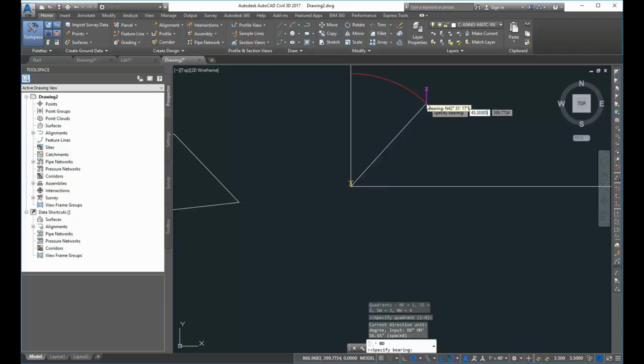So this is certainly different than what you're probably putting into your calculator. That reads as 45 degrees, 30 minutes, and 30.5 seconds. If my bearing was in decimal degrees, I would have to convert it to degrees, minutes, and seconds and put it in here. If you had a lot of them, then I'd type in units and override the default, but in general it's just going to want degrees, minutes, and seconds in that format, which is a little bit strange.